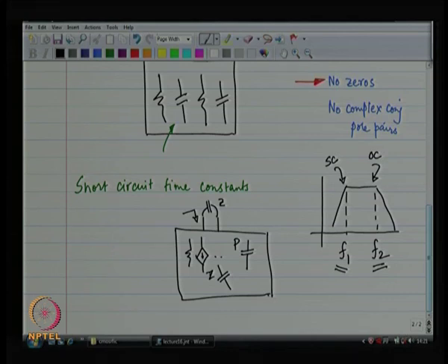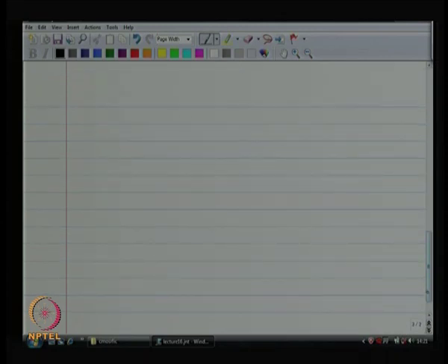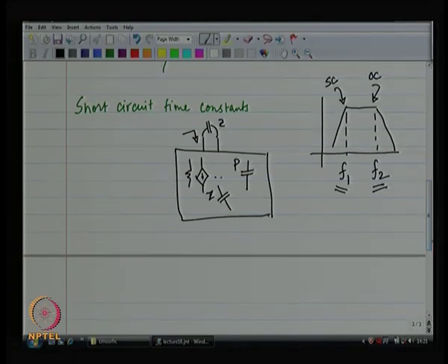Here the assumption is that my transfer function has only zeros and no poles. It is a very strange assumption, and that is how it is. So, we are going to assume that we have got everything only zeros in our transfer function. All right. So, these are all the 0 contributing capacitors. This is what it gives. You do not include the pole contributing capacitors in the short circuit time constant calculation. Similarly, you do not include the 0 contributing capacitors in the open circuit time constant, right.